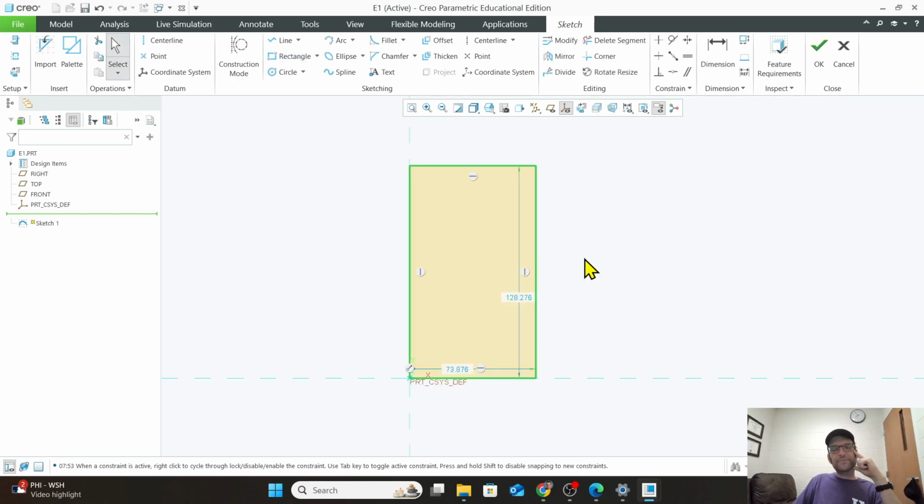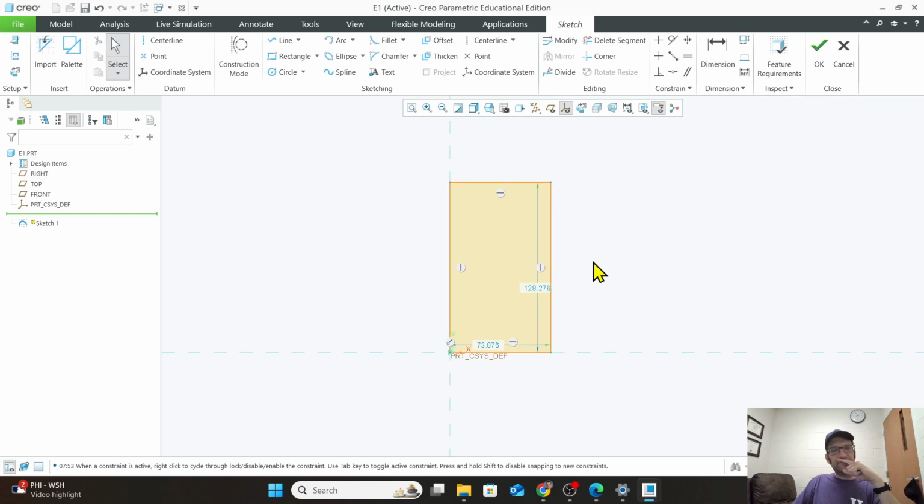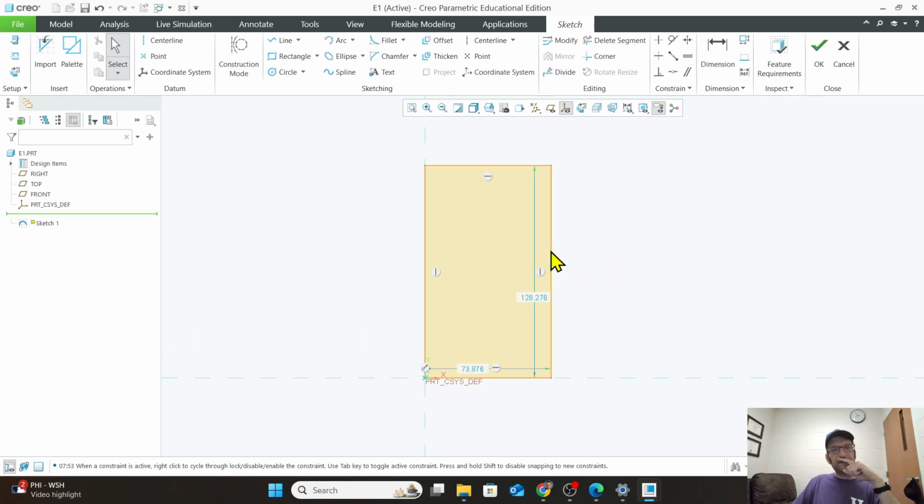All right. So here's where things get a little bit odd, for those of you that have done different stuff before. When we click on a line, we want to see the dimensions. So we want to click the center click, which is that center scroll wheel. If we left click on a line, we get some editing options that come up. We can add a dimension to that line, we can remove a dimension, we can do lots of things with that, but we just want to see the dimensions.